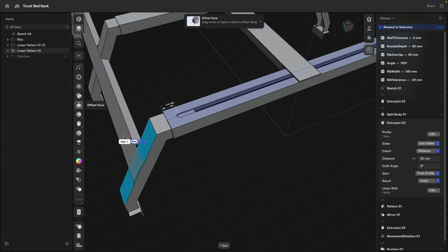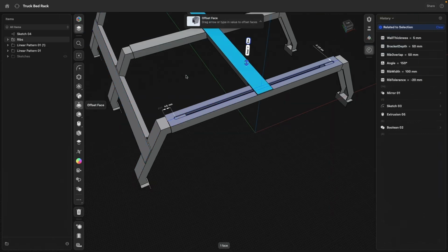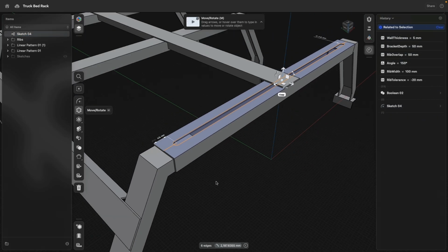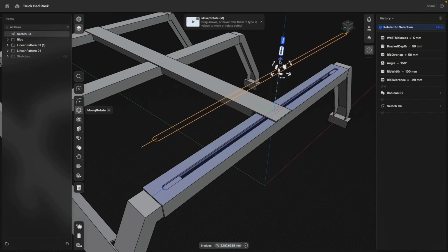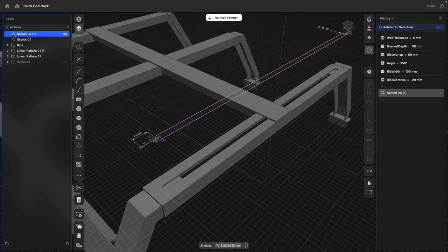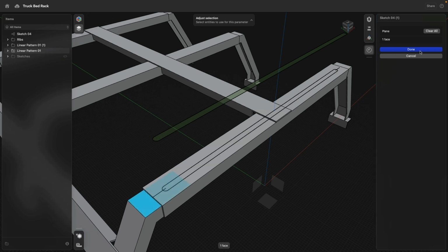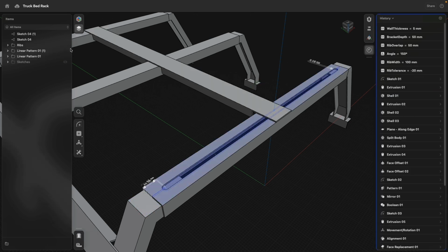So to produce actually the same pattern on these other faces, we can simply make copies of this sketch. And it's actually important that we follow a very logical system here. So I bring this one up a little bit on purpose, because you see by moving this up with a copy, it makes a new copy on a different plane. So this is a new sketch, and this sketch I can now project onto that face. Click done. Very good.